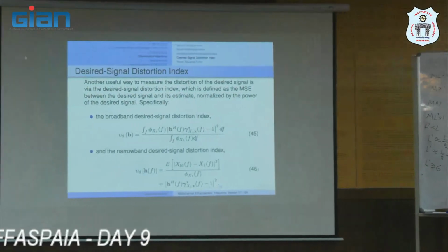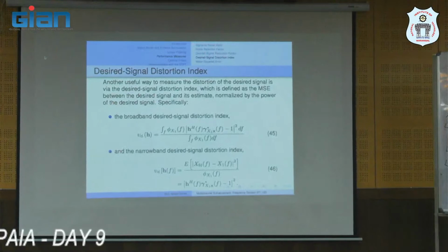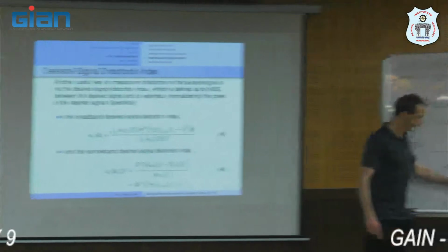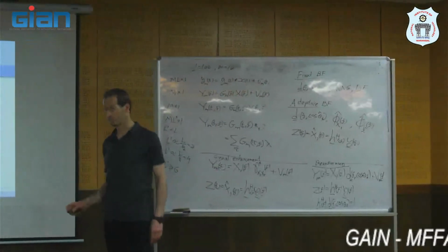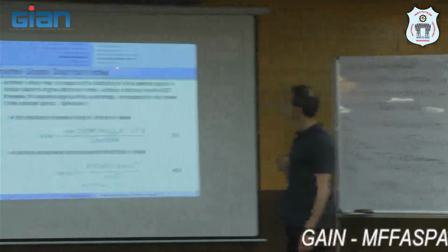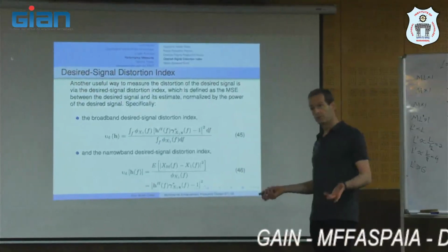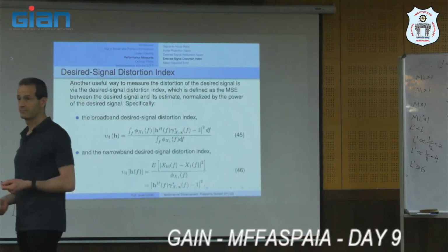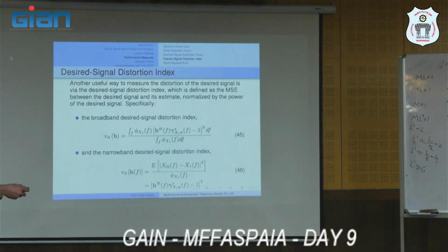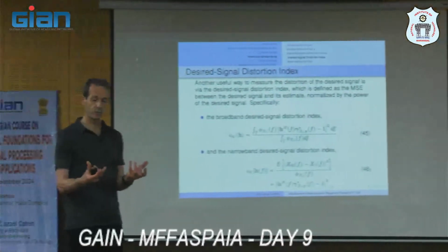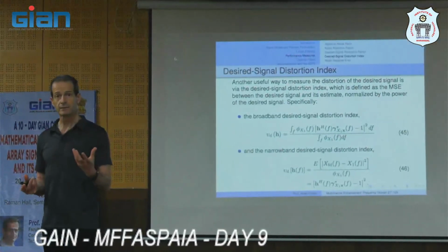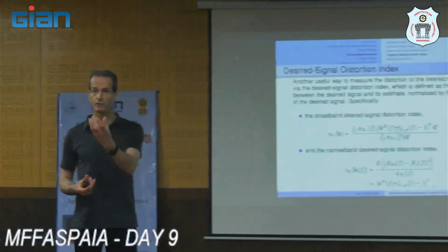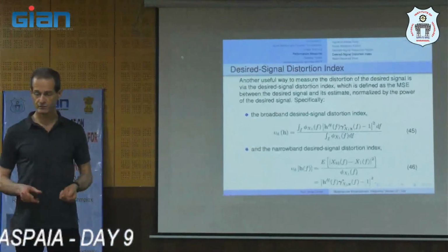Okay. So when we talked about signal to noise ratio, we can find a filter that maximizes the SNR. When we talk about the mean squared error, we can find a filter that minimizes the mean squared error, the Wiener filter. And then we said we can split the mean squared error into two components: the mean squared error of the distortion and the variance of the residual noise.